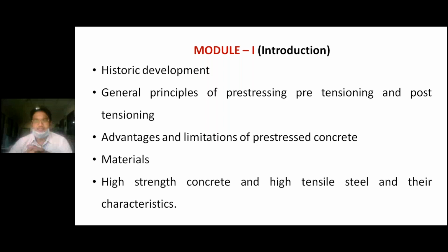I think you have seen L&T Metro, right? I will tell you one best example in L&T Metro. You have seen a center pillar, right? Adjacent to that pillar, there is a platform. That platform itself is a cantilever, and that cantilever was post-tensioned.